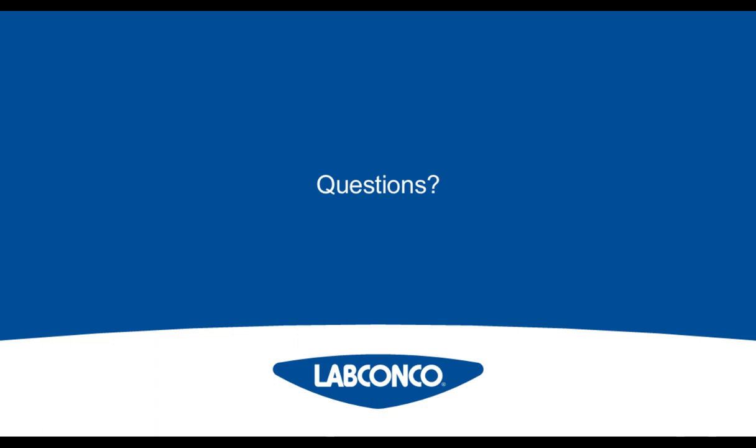So that's a great question. Obviously every lab has a lot of stuff in it already. I don't think I've seen a lab recently that has a lot of extra space on hand. So if your only option for any kind of containment versus open bench is a fume hood, the first thing you want to do is assess if you can make such a modification. And one consideration that you might be able to adapt is to add a filter in the ductwork. There are some manufacturers out there who provide in-ductwork HEPA and ULPA filtration options.